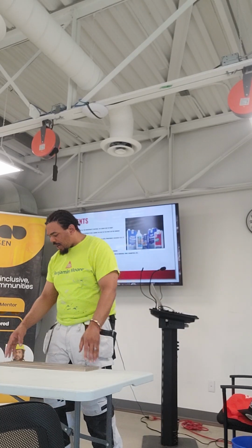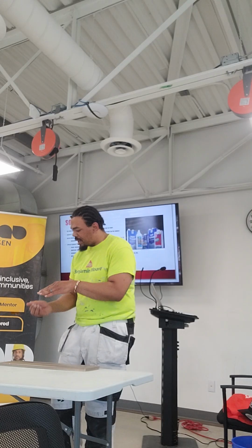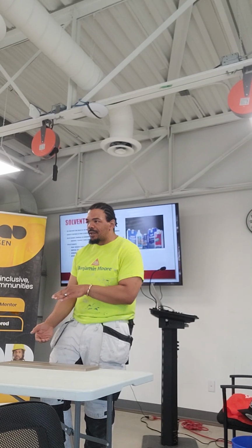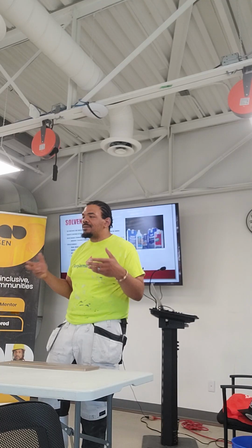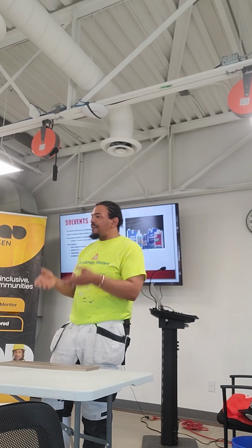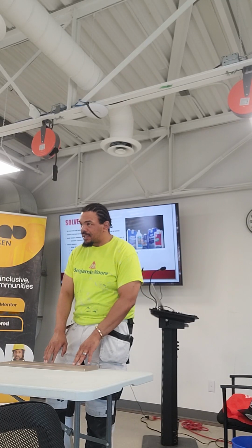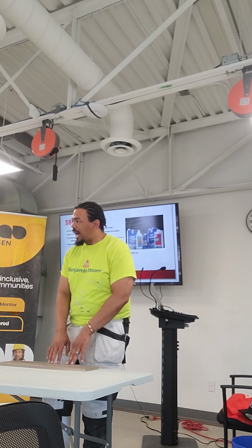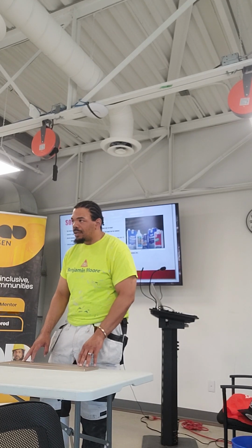And then when we spray it on, it sits on the surface. Part of it, because there's a chemical solvent, it melts into the surface like we explained yesterday. But then on top of it, everything gases off into the air. That's why we smell the paint when we're working. The paint is gassing off. That's the paint evaporating. That's the solvents evaporating off of the surface. And what's left is the binders and the polymers and all of the pigments that they put in the material.